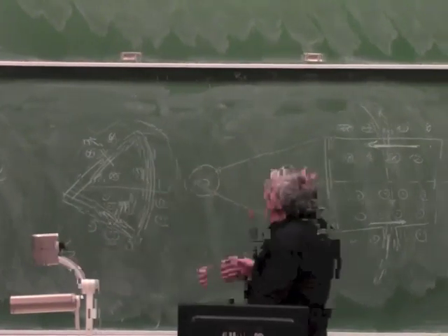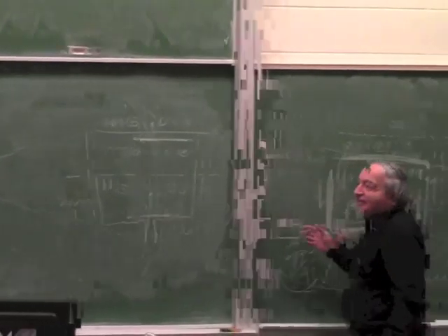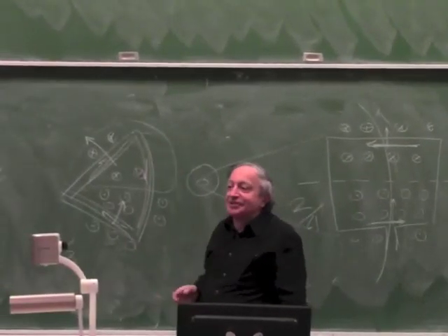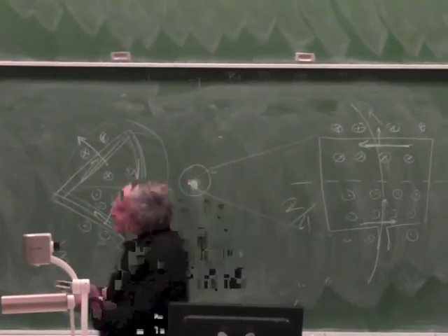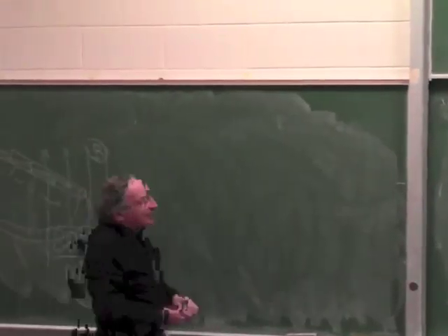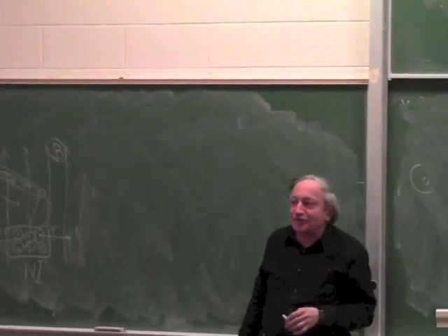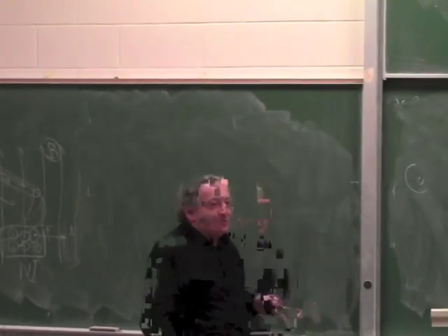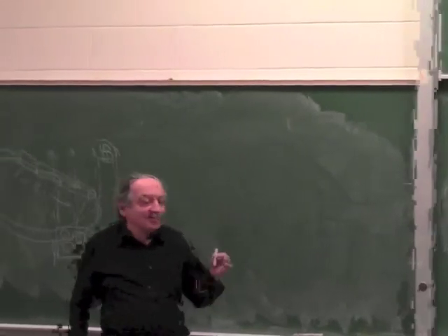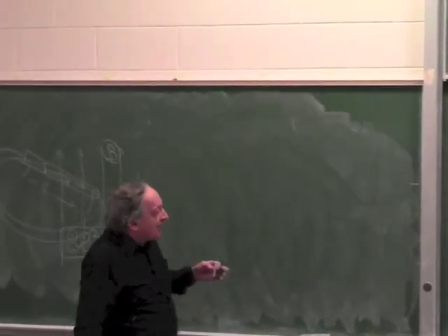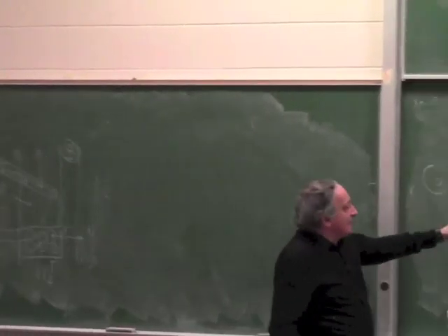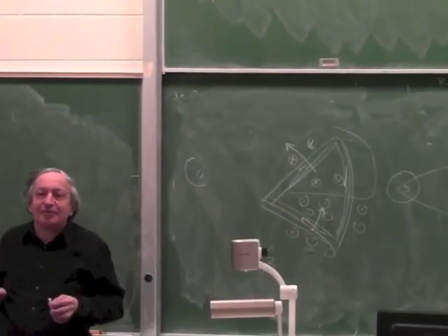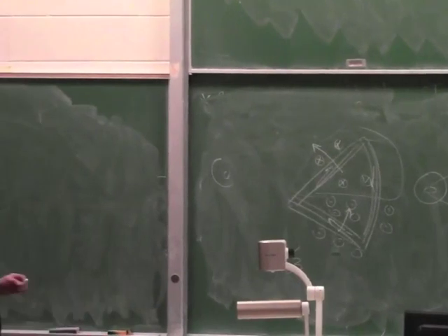What if we wanted to go back to a linear actuator, and we actually wanted every piece of copper to produce force? How do we do that? So something you all own, of course. Very simple. What we do is we do what a loudspeaker does. We lay out the poles of the magnet in such a way that the magnetic field is not parallel but radial.